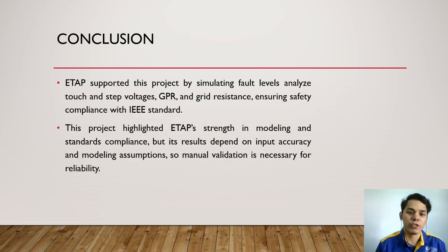Okay, so for the conclusion, ETAP has supported this project by simulating fault levels and analyzing step voltage, GPR, and grid resistance, ensuring safety and compliance with IEEE standards. This project highlighted ETAP's strengths in modeling and standards compliance, but its results depend on input accuracy and modeling assumptions. So manual validation is necessary for reliability.